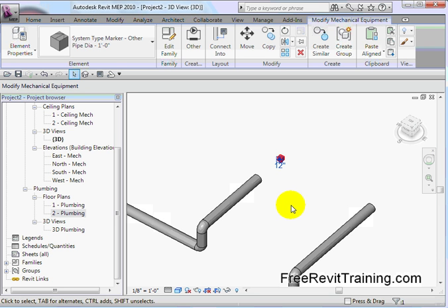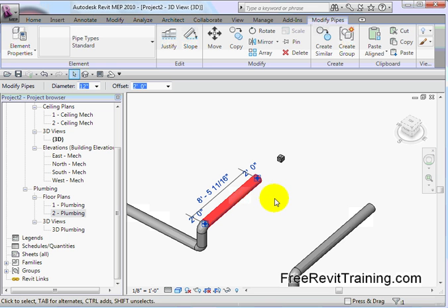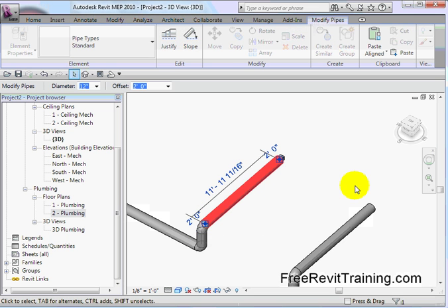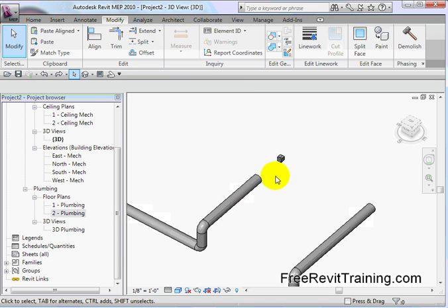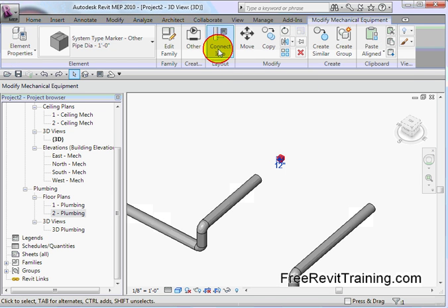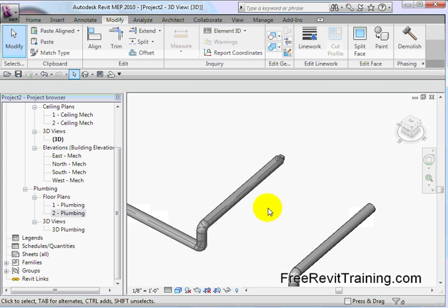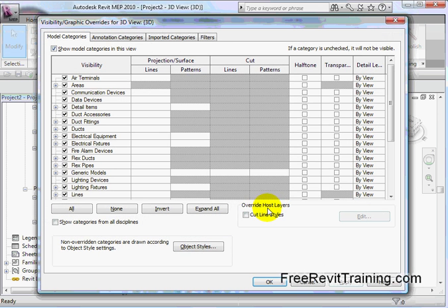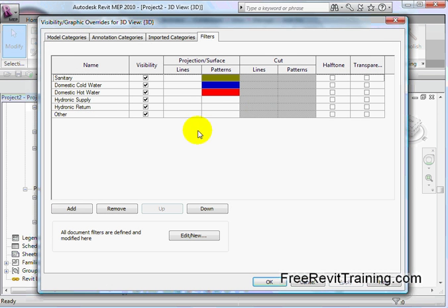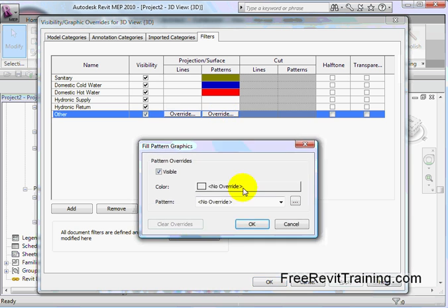Now what we need to do with the filters is do something a little different. So what we're going to do now is I'm going to grab here and we're going to drag this back, and you'll notice now actually we should connect it. That's actually a good point. Whenever possible, don't just drag them and try to connect them, because half the time they don't work. What you do is just tell it to connect to the system, connect into, and that way it'll blend in and it actually works. We'll type in VV and we'll make it go to Other, and then we'll create a new view to get fancy with the other stuff.